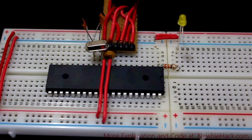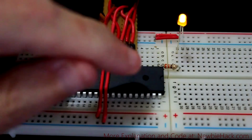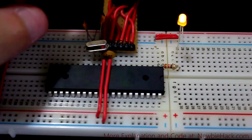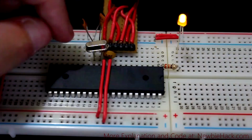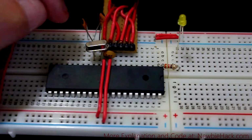Okay, the controller is programmed, and you can see that it is turning on and off at 1 second intervals again with the new 18.432 megahertz. Next video we'll be looking at actually doing the communication with the computer using the UART functionality, and we're going to be transmitting and receiving using the FTDI 232 chip or cable.